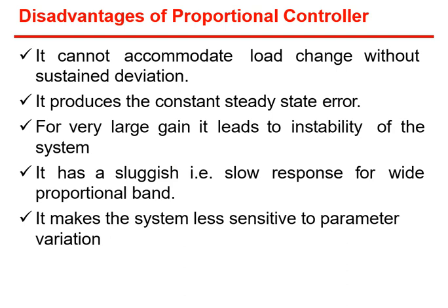What are the disadvantages of a proportional controller? Yes, there are disadvantages, and that's why they are not mostly used. The first is that it cannot accommodate load change without sustained deviation. It produces a constant steady state error. If there is an error, it produces that error constantly.